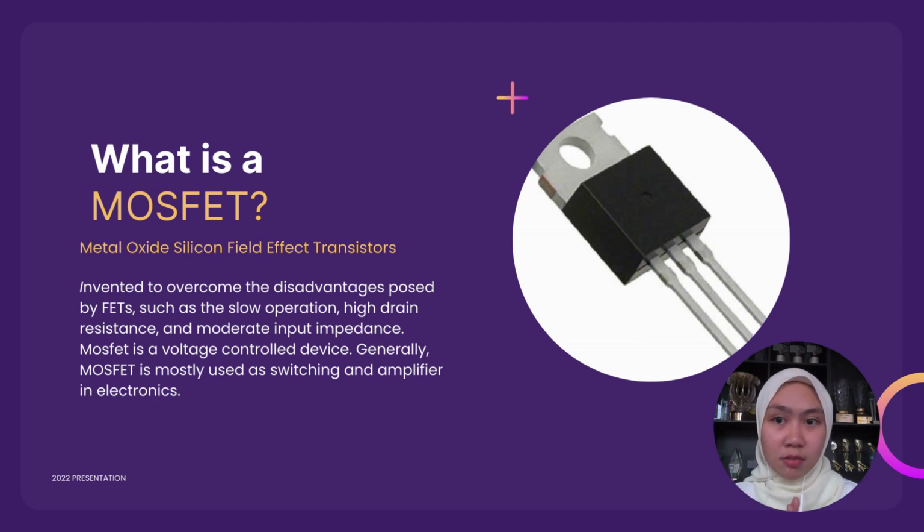Another type of transistor is the bipolar junction transistor, or BJT. Compared to BJT, MOSFET does not have the problem of the second breakdown phenomenon as in BJT. MOSFET generates much less heat loss compared to BJT at high currents, so it has higher efficiency than other devices. This makes MOSFET used extensively in power electronics.